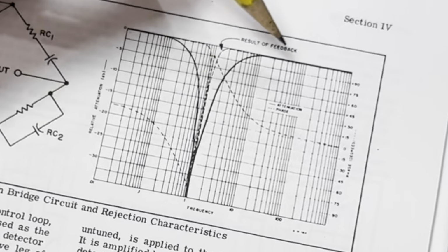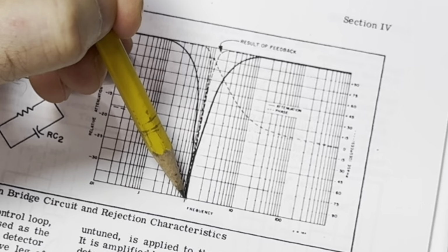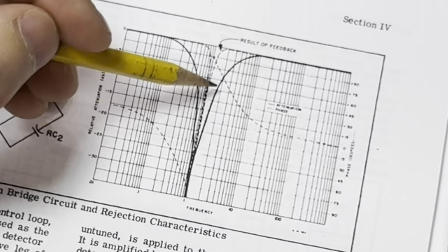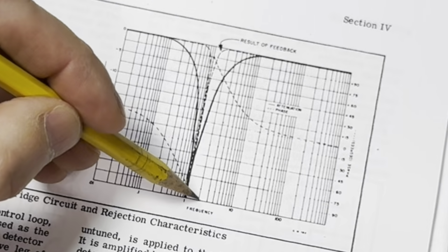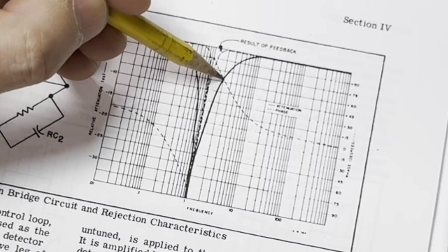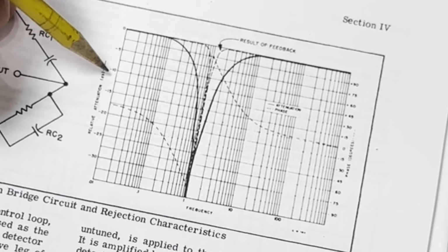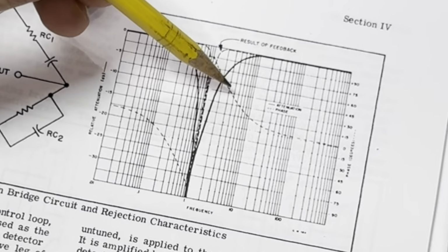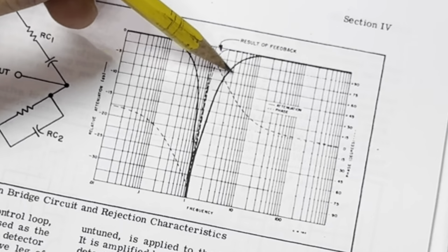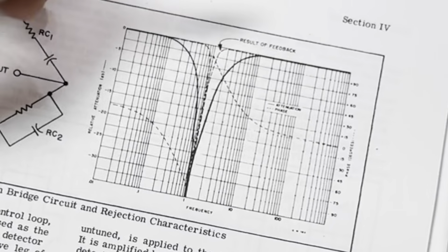But as we see here, our notch filter has a very deep notch at the tuned frequency, but it also affects our second and third harmonics and so on. As you can see from the second harmonic here, our normal signal level being up here, our second harmonic is attenuated quite a bit. This is about minus 7 dB or so of reduction. Our third harmonic has some attenuation here, fourth and so on, really till we get almost to the 10th harmonic before we start getting back to our normal signal levels.